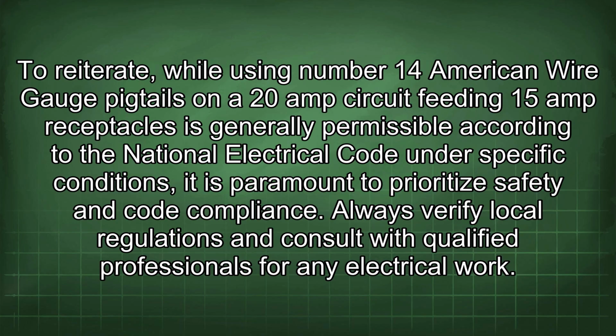To reiterate, while using number 14 American wire gauge pigtails on a 20 amp circuit feeding 15 amp receptacles is generally permissible according to the National Electrical Code under specific conditions, it is paramount to prioritize safety and code compliance. Always verify local regulations and consult with qualified professionals for any electrical work.